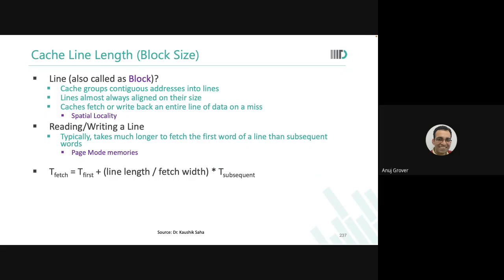It will be sequentially or parallelly? Each bit of the word. So, depending on the size of my bus, if my bus is 32 bits wide, I can get 32 bits in one go, at most. If my one word is 32 bits, then all the bits of one word are coming in parallel. It may happen that my one word is 32 bits, but my bus size is only 8 bits. That's a bad system design, but it can happen. In which case, even to get one word, I have to have 4 cycles.